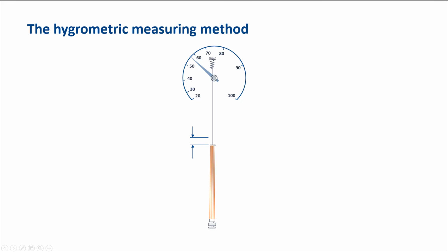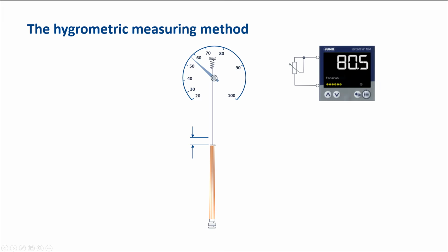The method contains a fiber whose length is influenced by the humidity. A special transmission system transfers the experienced change in length to a pointer or potentiometer. In the case of a potentiometer, the standard output signal is 100 to 138.5 ohms and corresponds to a Pt100 signal. The systems can be connected to evaluation units for RTD temperature sensors Pt100 and output a relative humidity of 0 to 100% for the resistance range of 100 to 138.5 ohms.